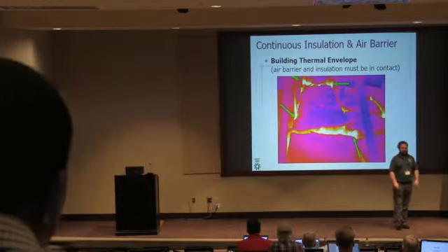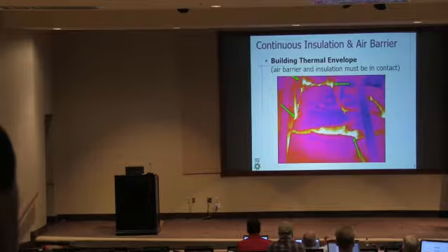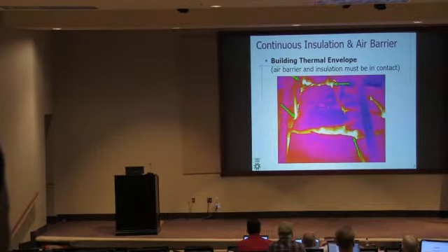We're looking at an infrared image here of an attic. It's cold, we're up in the attic, it's ventilated, it's winter. I can see the house is heated, and I can see all of this heat loss. Could be because of air leakage, could also be because this bat is not in contact with its air barrier. Got a piece of drywall, chipboard, trying to keep it 70 on one side. It's 40 degrees, outside air temperature on the vented attic, on the other. Conducts through that little piece of chipboard.